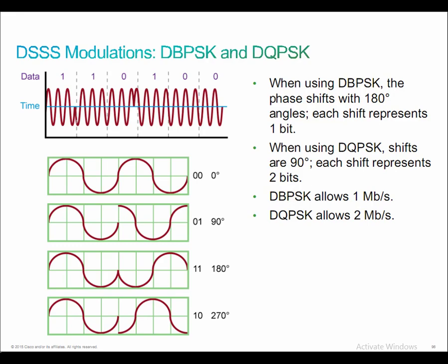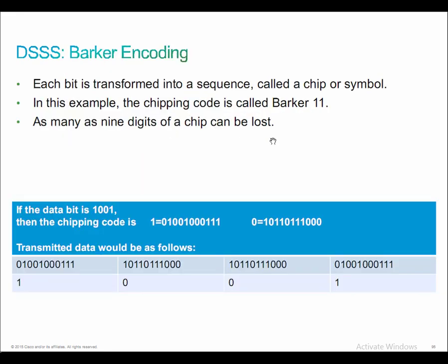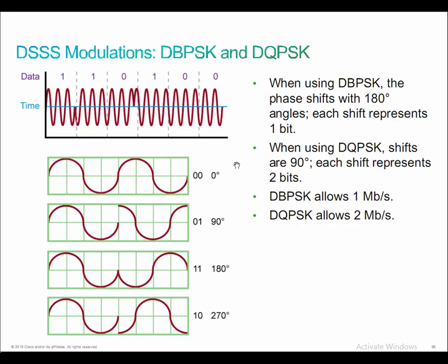And there's actually a couple of different steps that are used for this process. We start by grouping individual bits of the symbol into groups of 2. All right, so let me break it down. Let's just point at it here, right? If the chipping sequence is being sent as this or this, we're going to break up that chipping sequence into groups.